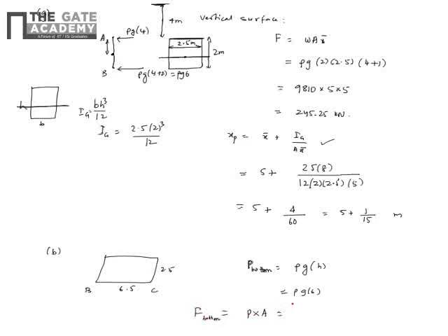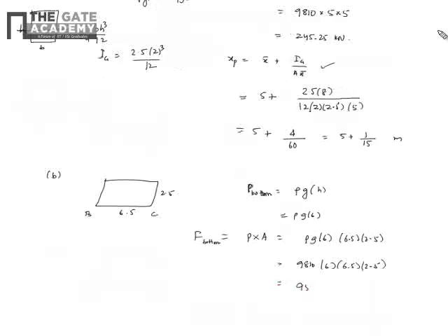So this is a horizontal surface, so straightforward. Rho g times area is 6.5 into 2.5. So you get 9810 into 6 into 6.5 into 2.5. So let's calculate it. So we get 956.5 kilonewton as the force. So this is a very simple problem. On the horizontal and the vertical surface it will be given, you have to just use the formula and just calculate it.